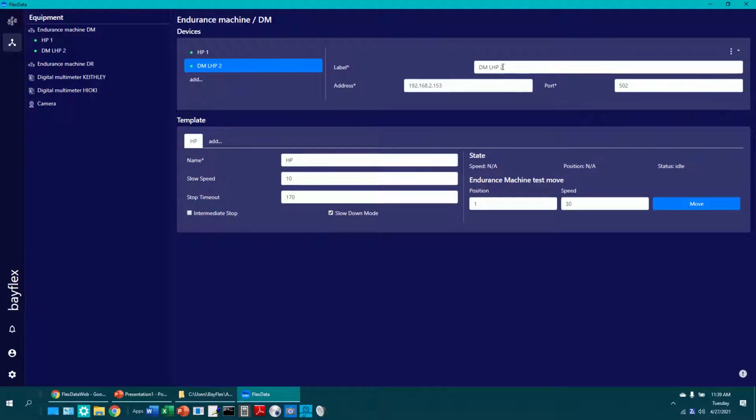The HB and DLDM and TCDM have analog motors, and they behave differently from the HP, which has a stepping motor. If the analog motors are running at high speed and they are given a command to stop moving, they slow down and coast to a stop. They do not stop suddenly, and they will coast past the desired stopping point. The exact stopping point depends on the individual motor and jig. For an FS, the desired stopping point is when the sample is flat. At slow speeds, the HB will stop before it reaches the flat position.